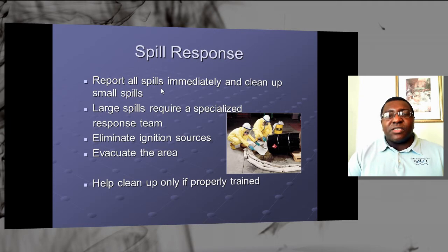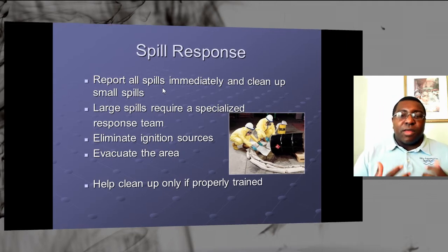If you need to throw down some quick dry or kitty litter to absorb some of that liquid, that's what you do. On your SDS sheets, they have a section specifically for cleanup. So review your SDS sheets and find out what you're dealing with, because if you're adding chemical to something that may have a water-activated flammable vapor, then you're doing the wrong thing, and that's not what you want.